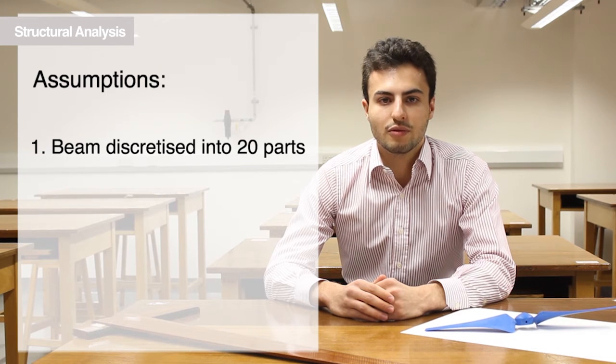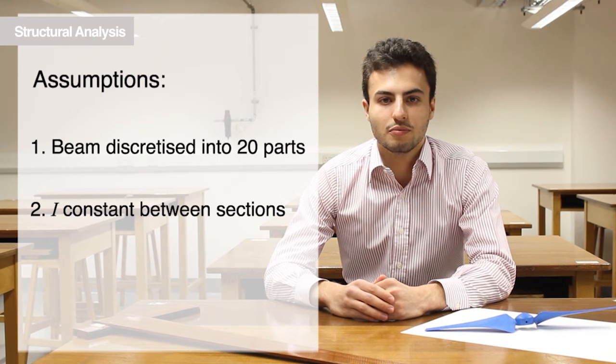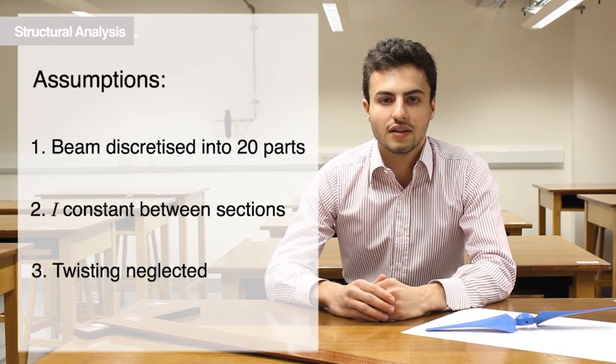First, the beam was discretized into 20 parts. The second moment of area was assumed constant between each section, and lastly, twisting was neglected during testing.